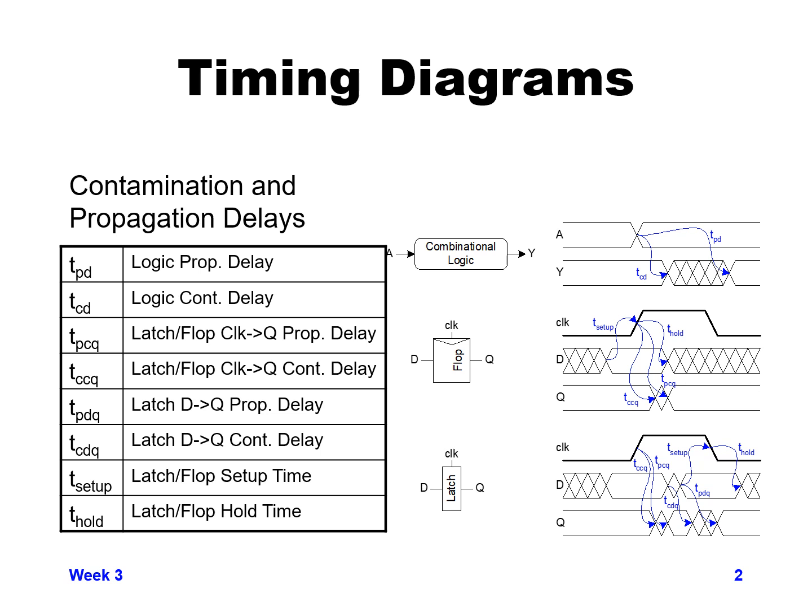And then finally, you have the two setup and hold times, where since a latch does the final capturing of its data value based on the closing edge of the latch, so the clock falling, we need to make sure that data is not switching during the time that clock is falling. So data has to be held stable so that we get a known value that is going to be held in the latch during the time that the latch is closed and the clock is low.